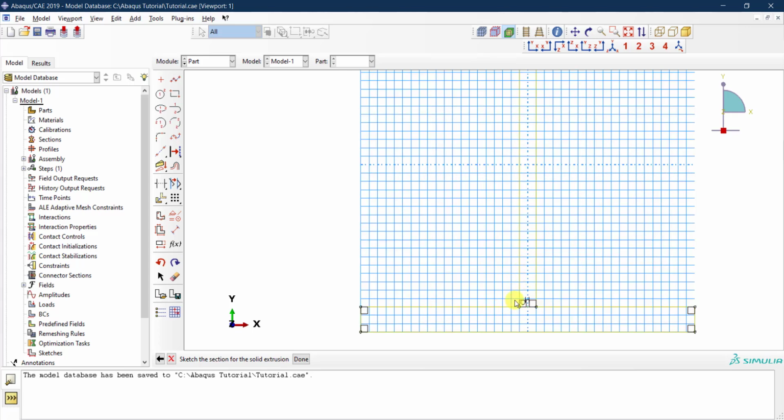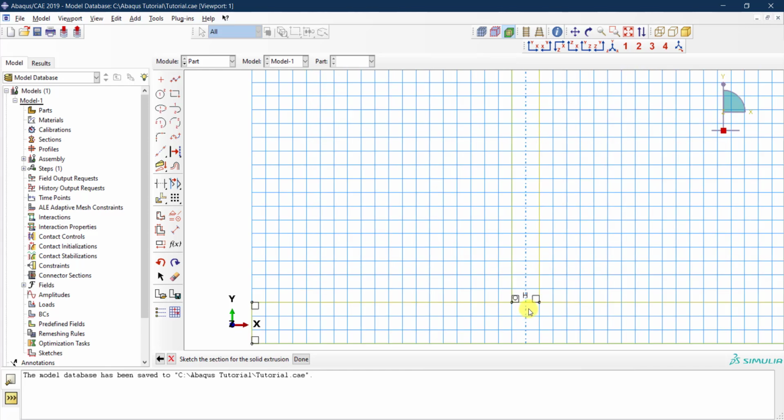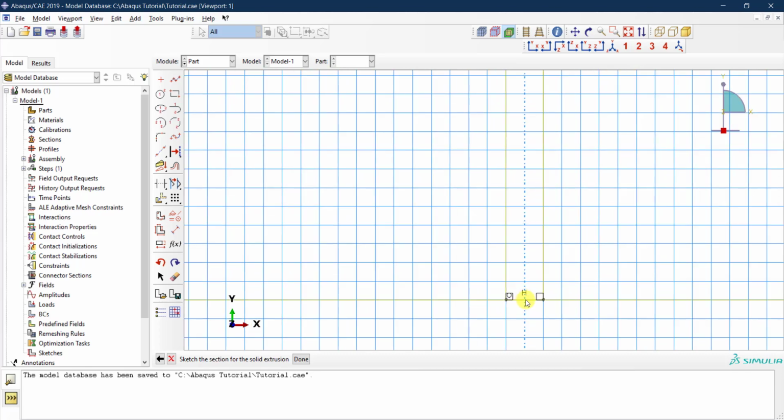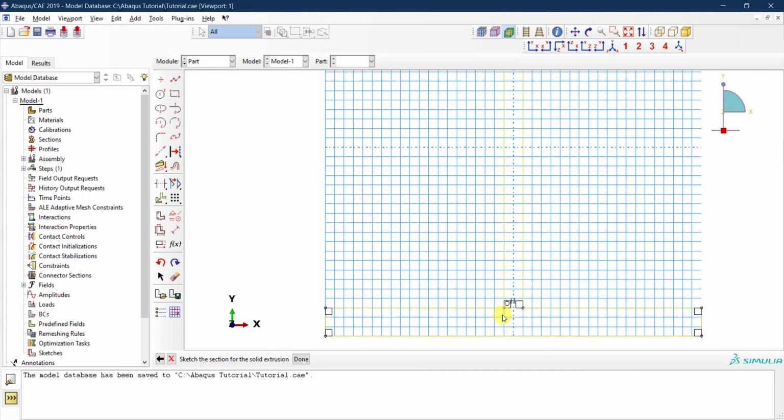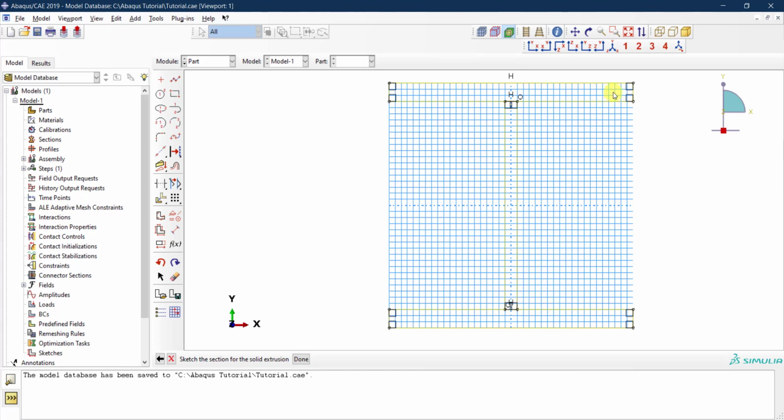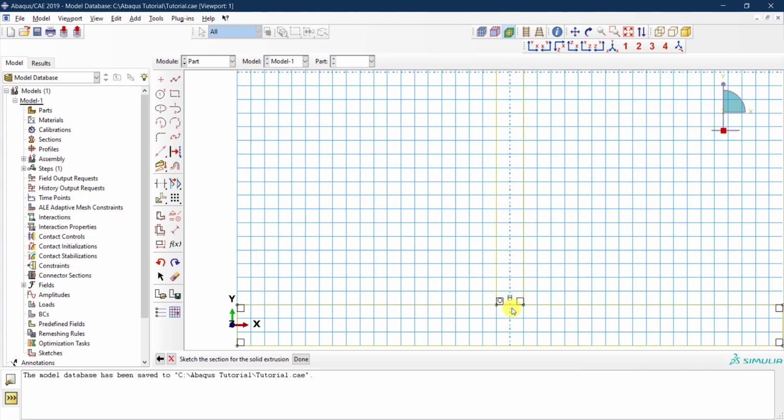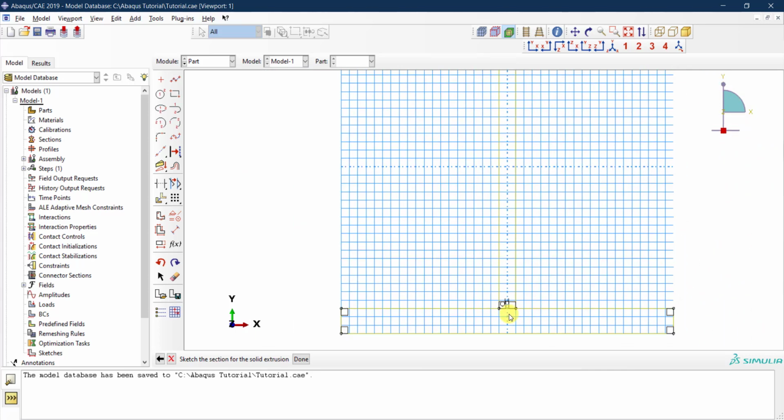So right now we finished the flanges and the column, but of course we still don't have the radius yet. Okay, so the fillet radius, we need to model this. We have fillets at the edges, and at the same time, I have a line over here, but this is not good. In order to do a solid extrusion, the area inside needs to be a continuous area. So you need to have a unique perimeter around the section. So right now I have this line between the two parts, so this needs to be removed.